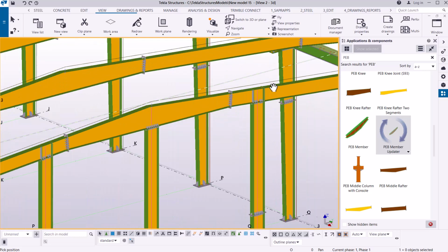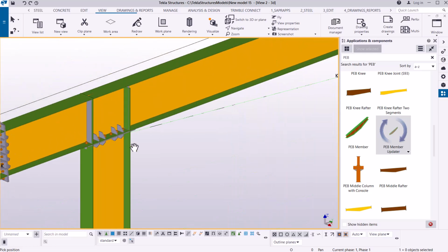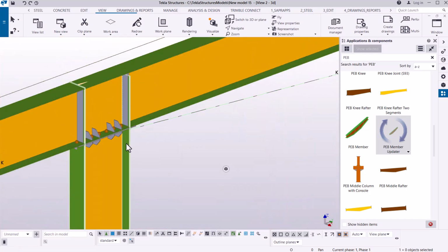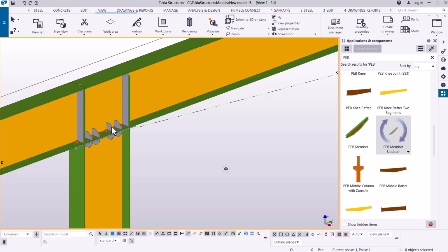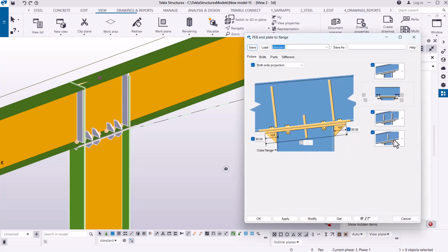I can see even in the opposite direction here, we still have these components, this member protruding all the way up. So it's always advisable you counter check your connection prior to moving ahead to a different step. So in here, I'm going to just disable that and click apply, and let's see what's going to happen there.